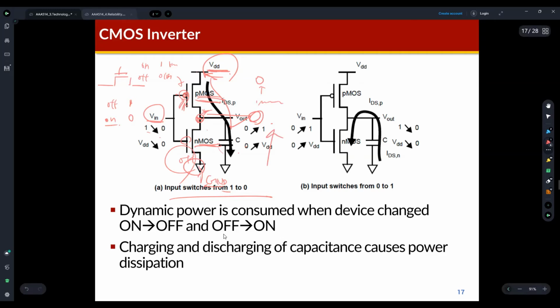This means if the input becomes 0, the output becomes 1, VDD. It's the inverse: if the input becomes 1, the NMOS transistor is turned on and the PMOS transistor is turned off. The node of the parasitic capacitor is connected to the ground, so the electric charge is dissipated from the capacitor, which means 0. This is how MOS transistors work in a digital system.